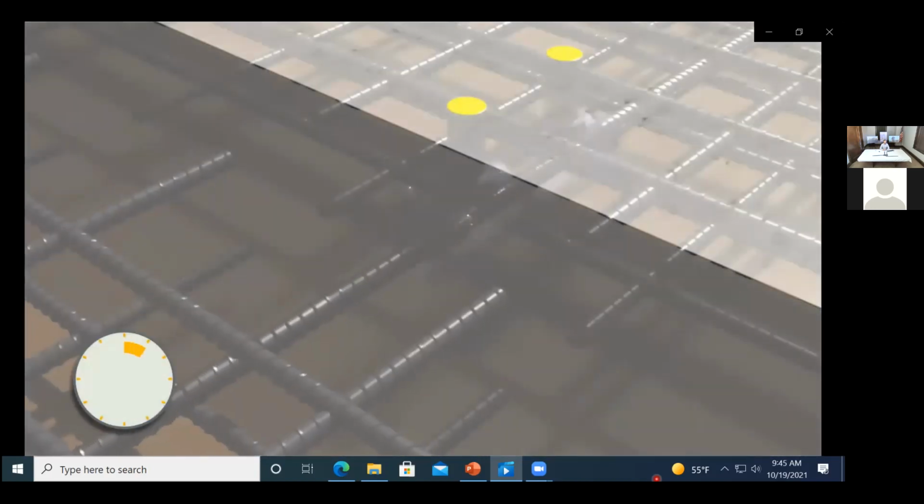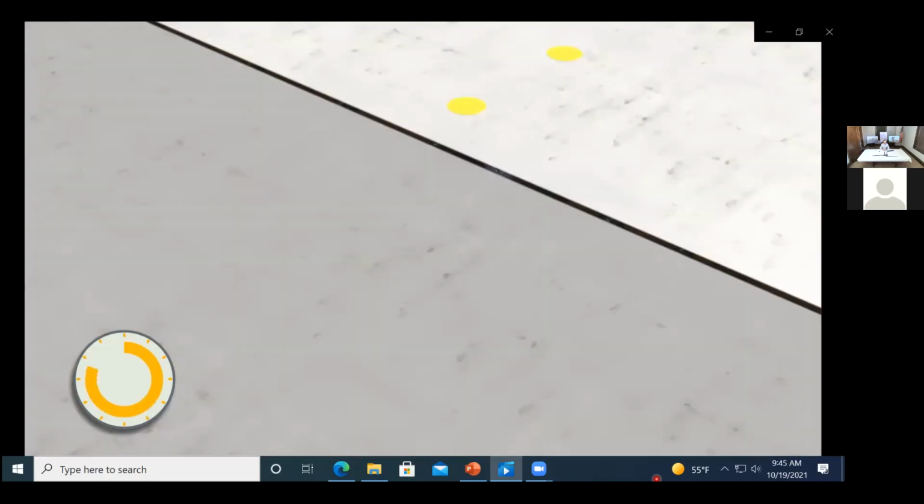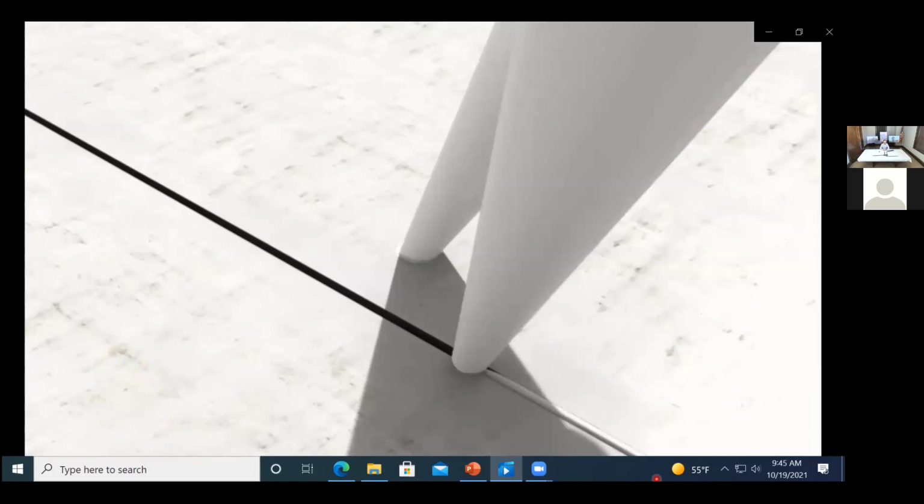During the specified amount of time, the joint opens up as the concrete shrinks, without the need for traditional pour strip formwork. The couplers and joint are grouted, creating structural rebar continuity without significant reforming of the pour strip.